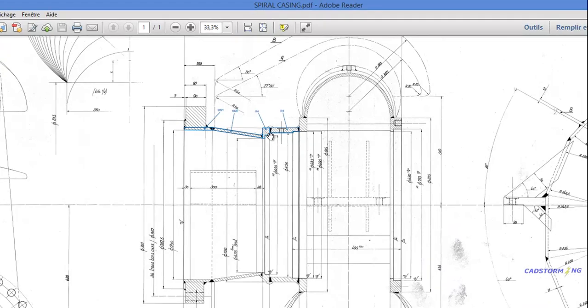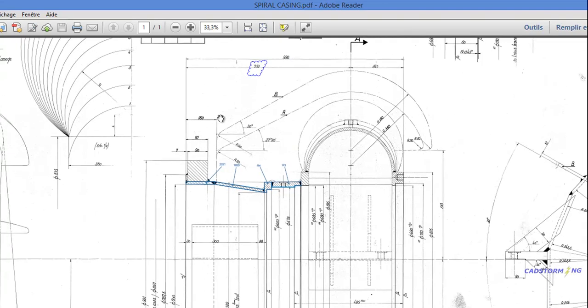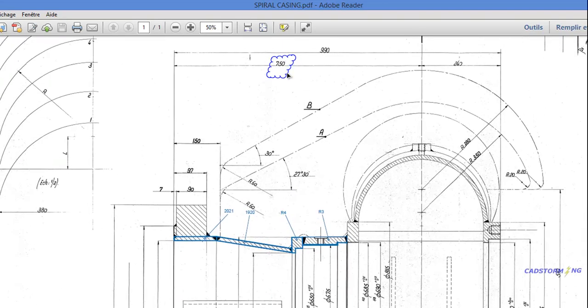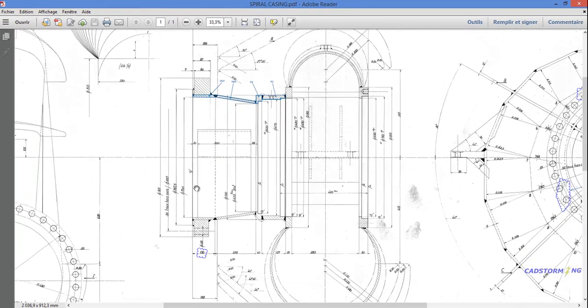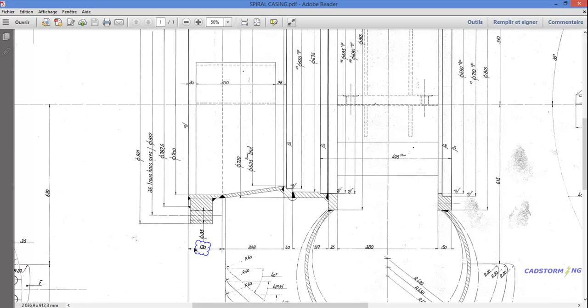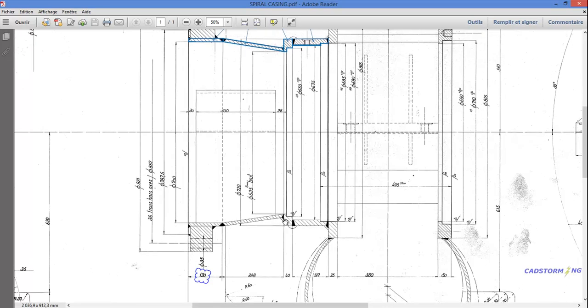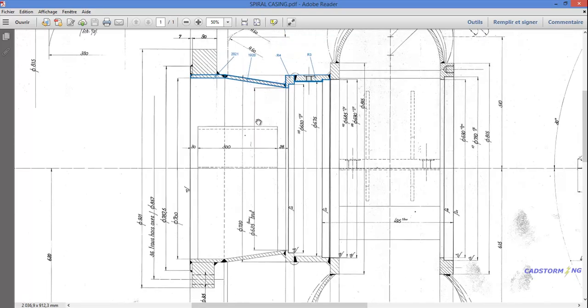Now we are going to create these two sheet metal components, and to do that we are going to first create a parallel plane at 750 from our coordinate system, and from this parallel plane we are going to create another parallel plane at 130 and a coincident plane right at this face of this component.